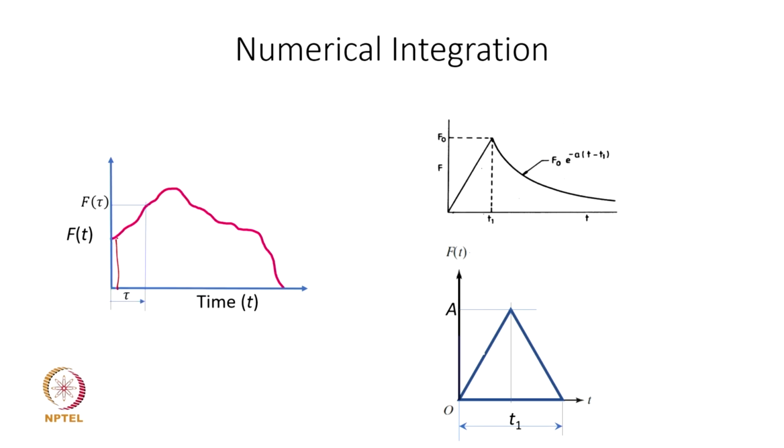So, instead of some mathematical expression that we have seen how we use for this kind of a triangular waveform, we may discretize this into very fine time intervals and then simply sum up the total response doing it numerically. So, using the numerical addition of individual response expressions, we can find out the response to a truly arbitrary excitation.